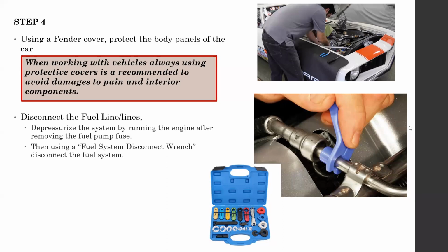Whenever you are working, especially on cars with the hood open, you always have to cover the fenders. I'm guessing you know what a fender is. You cover the fenders to avoid any damage while you are working on the vehicle, right?